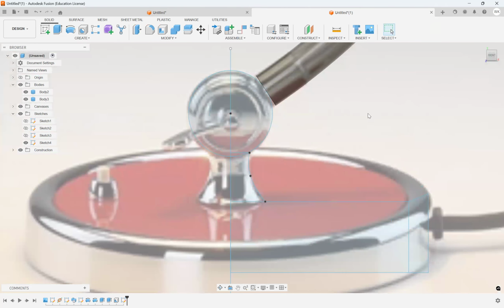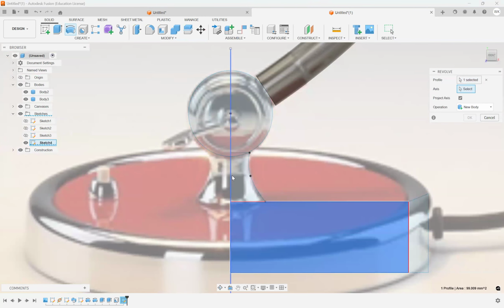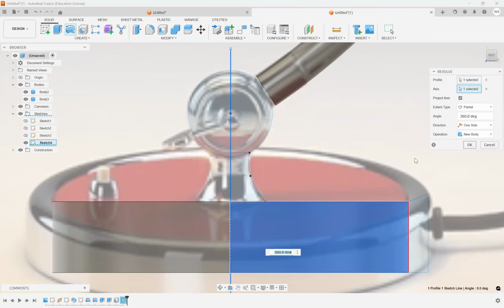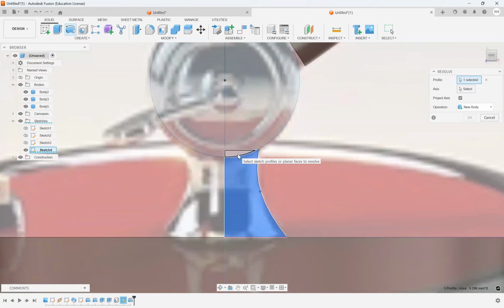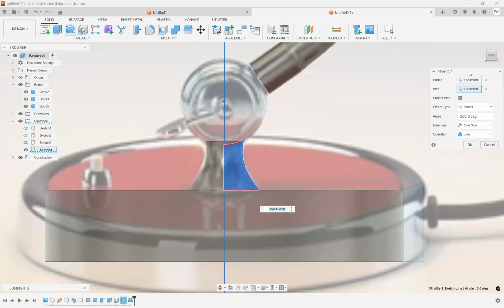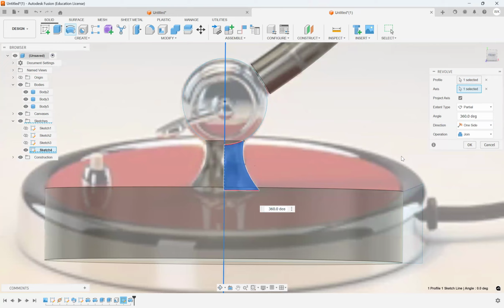And finish the sketch. As you can see here, we can use the revolve tool for our main body, re-show the sketches and create a metallic sheet. And the important part is that since it looks like this neck part and this red part are separate, right?